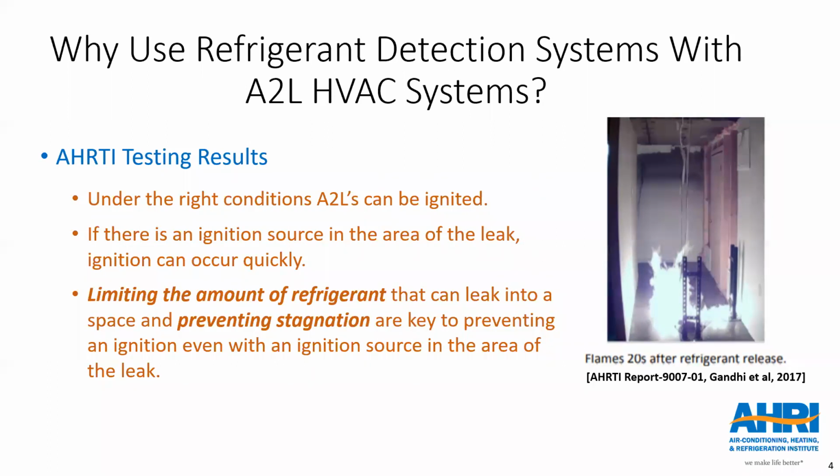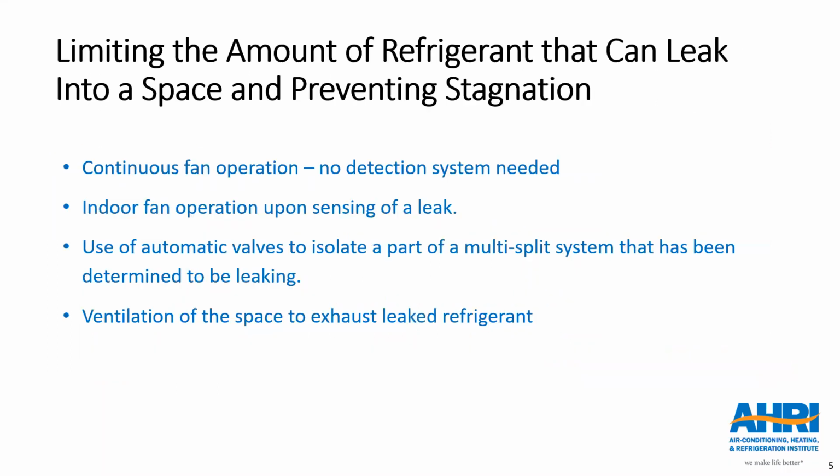Because of this, the safety standards include detection and mitigation as a key requirement for equipment that uses A2L refrigerants. Now the next slide will show the basic ways that are available to mitigate the risk when there is a leak.